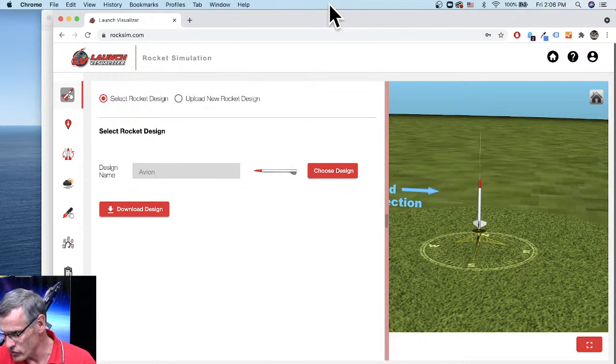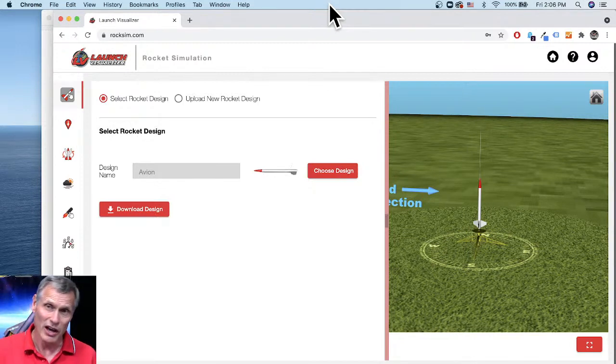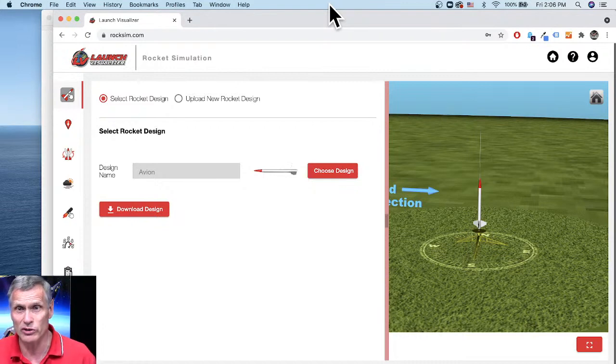Okay, piston launchers and short duration weights that detach as the rocket rises are two different things. A piston launcher imparts extra velocity to the rocket. That's used in competition rockets because you want to get as much energy out of the launch as you can.